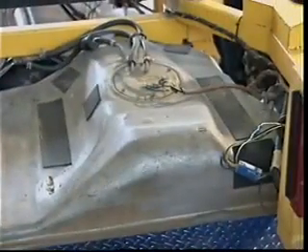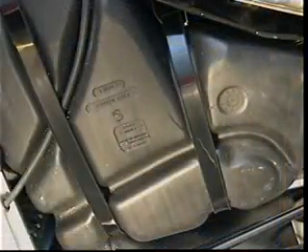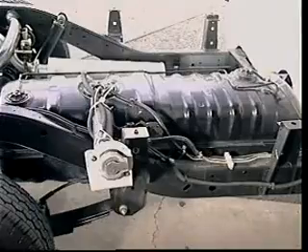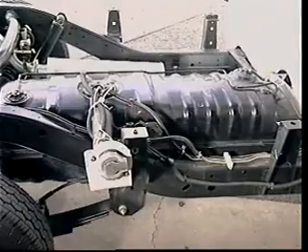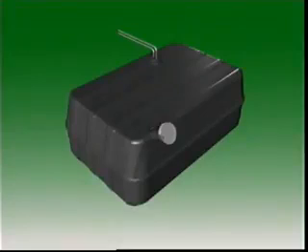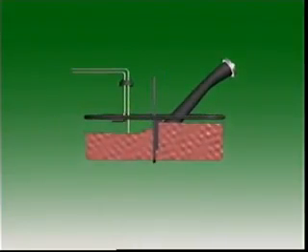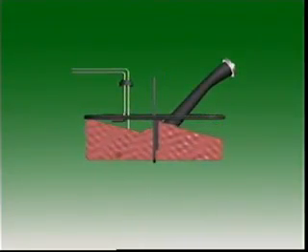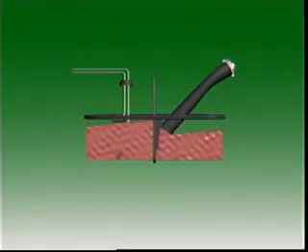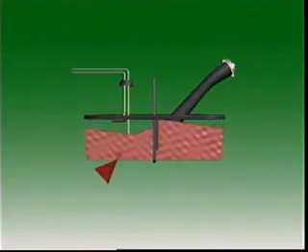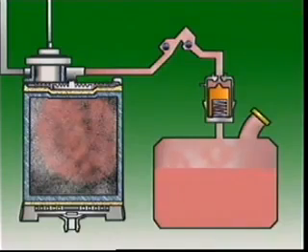Most tanks are made of tinned sheet steel that has been pressed into shape. Some passenger car tanks are made of non-metallic materials. Aluminium or steel is used on commercial vehicles. The tank is usually in two parts, joined by a continuous weld around the flanges where the parts fit together. Baffles make the tank more rigid. They also stop surging of fuel and ensure fuel is available at the pickup tube.